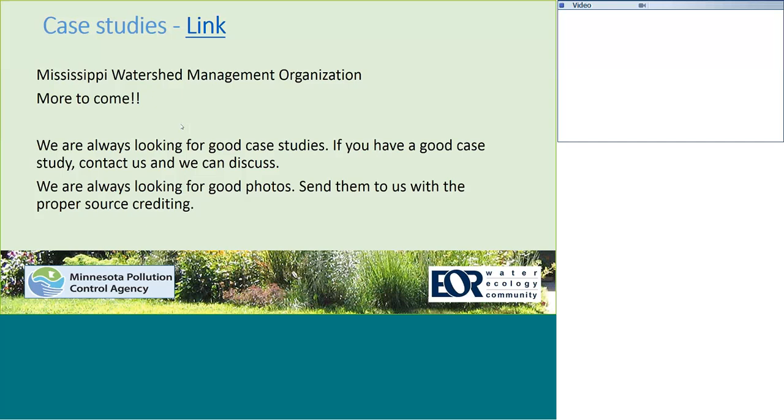Any other questions? How is the waste stream handled from backwashing filters? Good question. It depends on what you're backwashing out. Sometimes it ends up going to a sanitary sewer discharge, depending on the volumes and the site. If it's not too terribly bad, you might find another way to dispose of that. But I'd say if you have a fairly large system, it most commonly goes into a sanitary discharge.